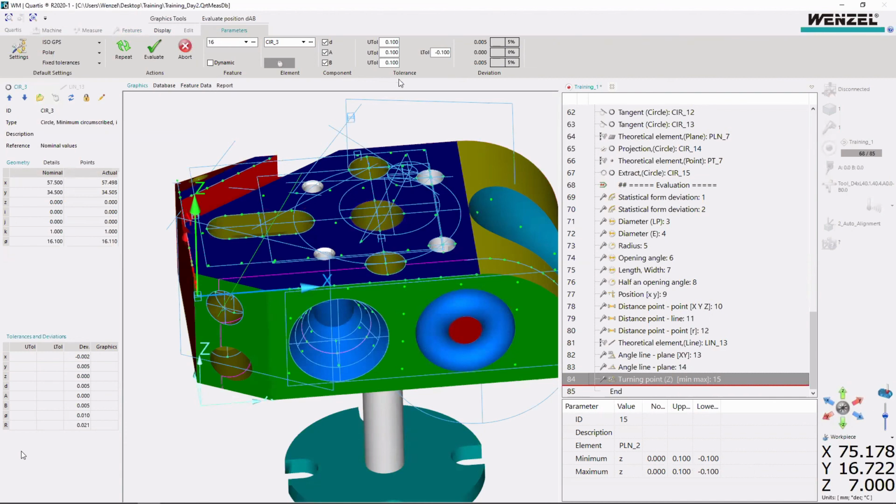So you will see there is some deviation D, which consists of A and B. A is 0 because the circle is projected upwards also, so there is no difference in the z-axis in this case. So A is 0 right now, and B is 5 microns.